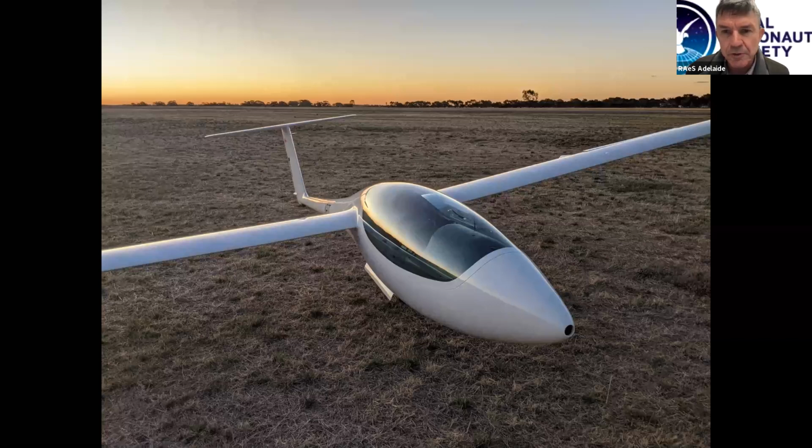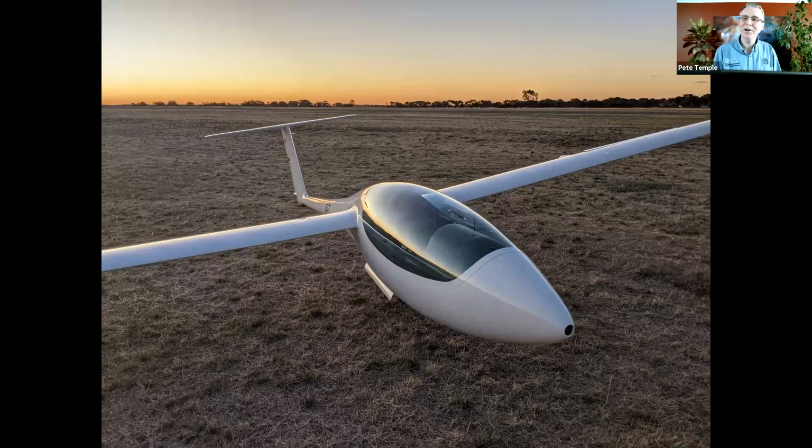Fantastic. Alan Wilson makes a comment that we look forward to the day when CASA integrates FLARM into their radar surveillance for RPT awareness, and thought you gave a good promotion to that. Well, whether CASA is going to do that, I don't know. What is actually happening in future is probably more the other way, is that more and more gliders will get ADS-B, and in particular ADS-B out, which means that we'll then be using a system that's compatible with CASA, which FLARM is not, and they'll be able to see us through that.